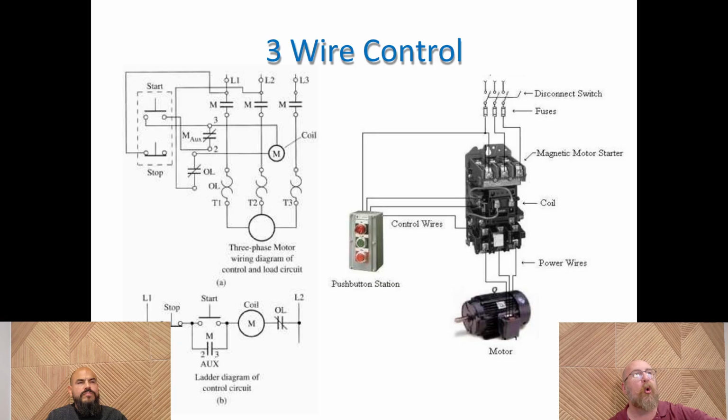And so we create an OR that is part of the line of control using the coil itself. So the normally open contact on that is going to be added. Essentially, we wire that into our start and stop, so that if we press the start button and it is running, that contact becomes closed, and then it can be either that contact or the start button that keeps it going. So we can let off the start button and it will continue to go.